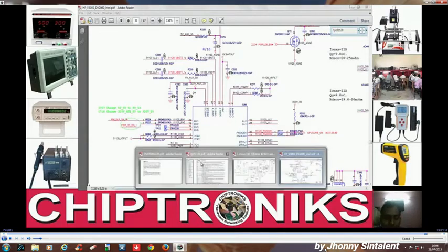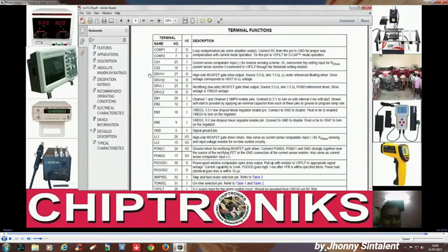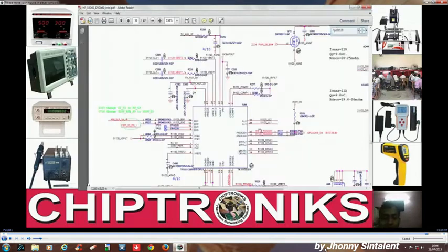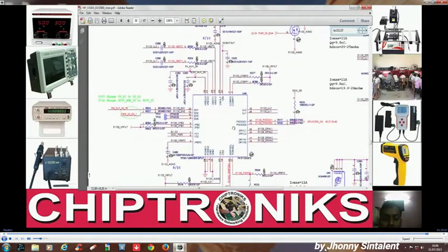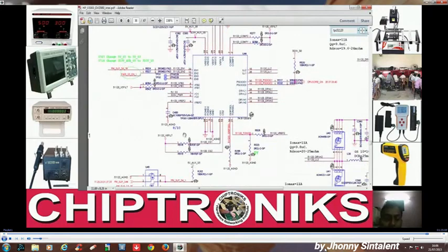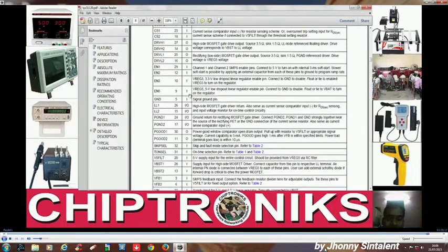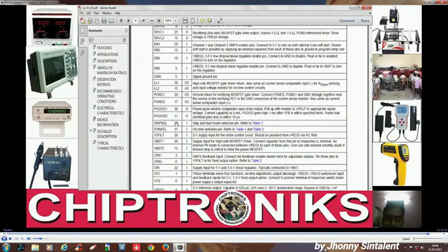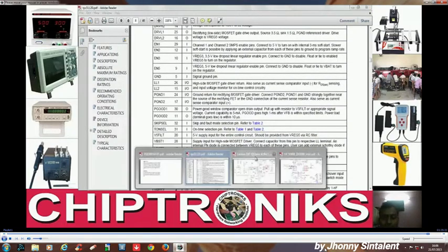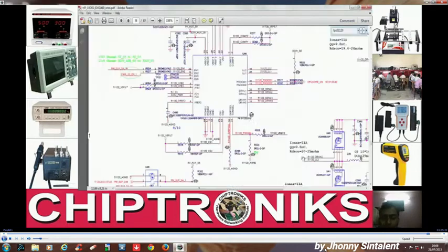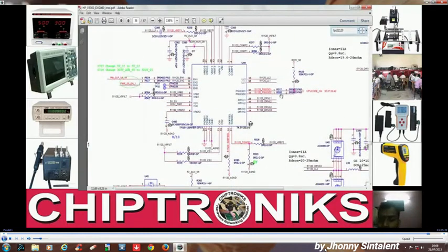So we'll go again to the data sheet, and we have CS1 and CS2, the current sense comparator input. This part was also not available in RT8206L. So let's see CS1 and CS2. This is CS1 and CS2, again connected to the 51120 FILT. Okay, and enable we have already discussed. P ground, P good 1 and P good 2 is similar. Power good 1, power good 2. You see over here, power good 1, power good 2.